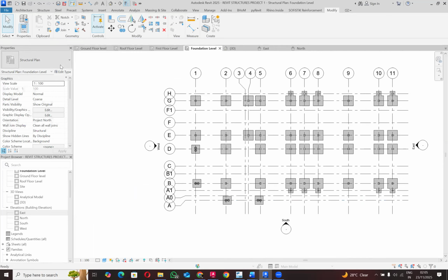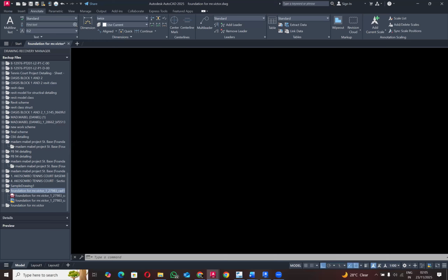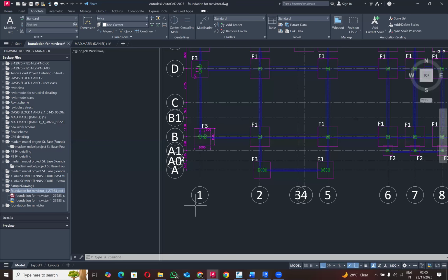Let's connect this by a strip. Okay, let's model the strip. Our strip has a width of 450. Strip has a width of 450, standard measurement. So strip 450, and then depth of 200. Or you can use 150. So you can use 450 by 150. Okay. So strips.